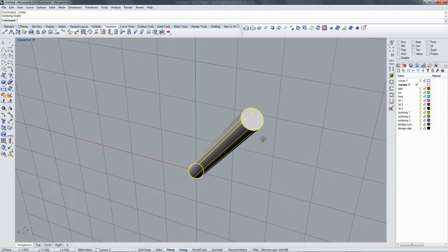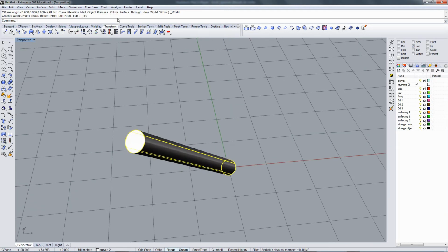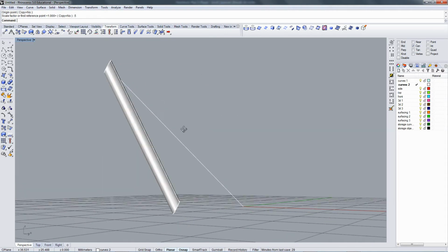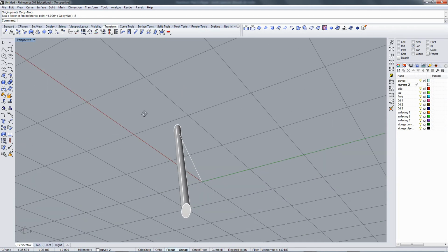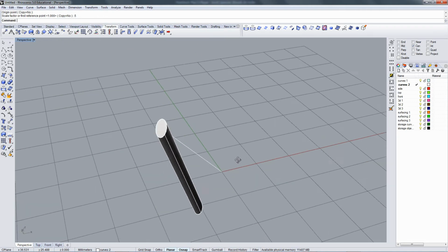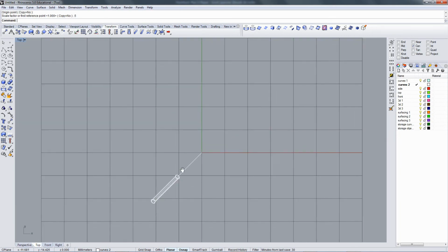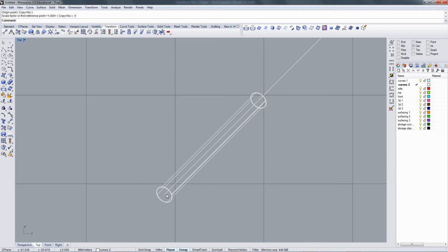But let's say I'm going to try and do this now with a 2D scale, so we don't change the length. That's clever. I like that. Right click on our 2D scale here on our scale button. Snap to the center. 50%. Oh, hang on. I didn't have that set to 50%. Perfect. See what happened? I did keep the same length, but it skewed the geometry because it's thinking 50% from the top. It's doing it all from this direction.